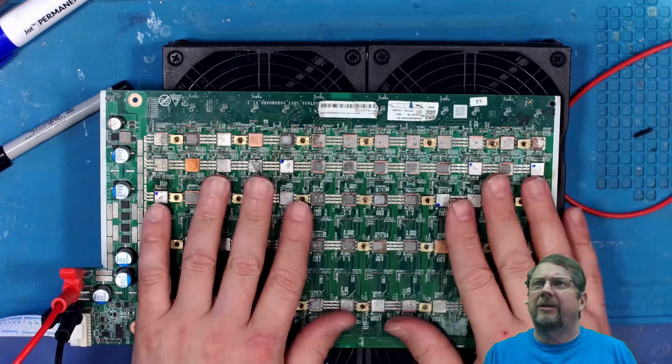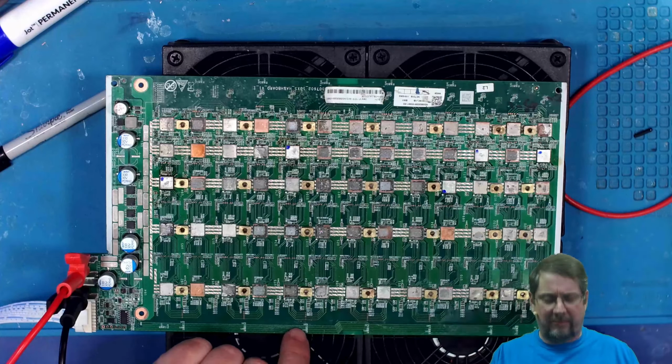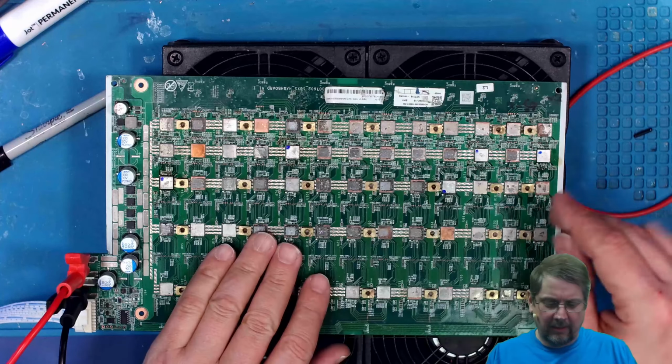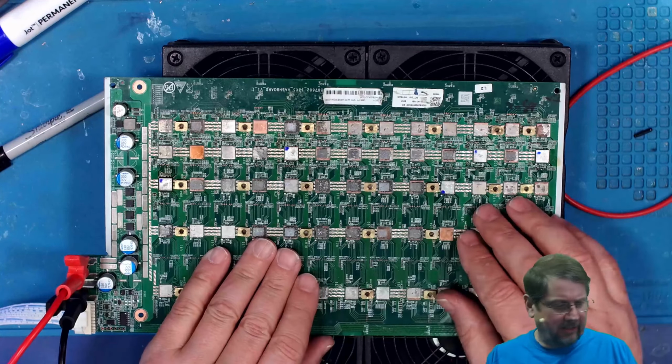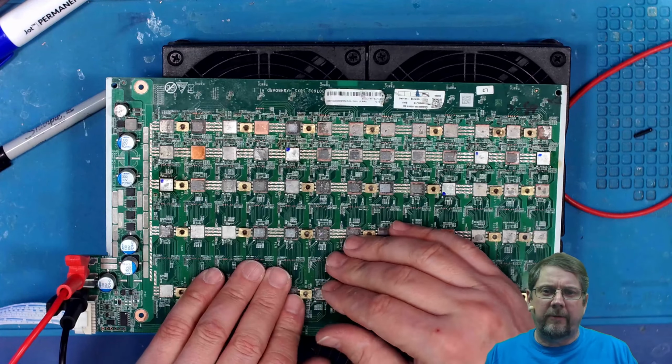Okay, there we go. So that was it. 5 chips. Took them out. Some of the chips you may have noticed in the soldering, I would desolder, and others I just put a little flux on there and I cleaned them up. Those were ones that I had previously pulled.